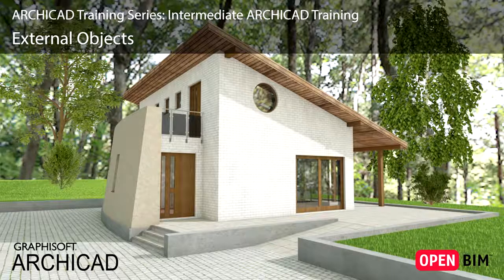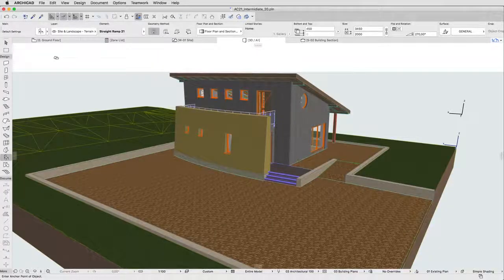In this lesson, we'll learn how to use the ARCHICAD Library Manager. We'll then place some site elements and fill the internal spaces of the building with furniture objects. The ARCHICAD library contains a wide range of objects, including furniture, sanitary fixtures, special building structures, site elements, and so on. The standard ARCHICAD library loads when you open a new project.